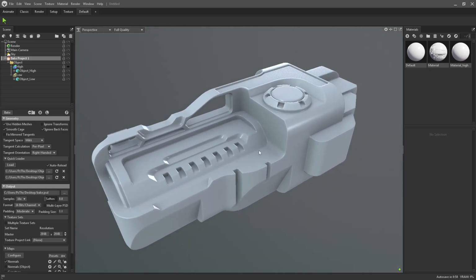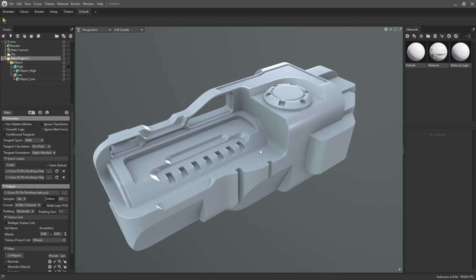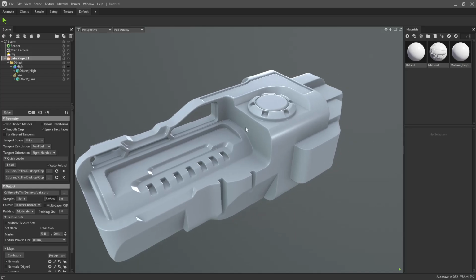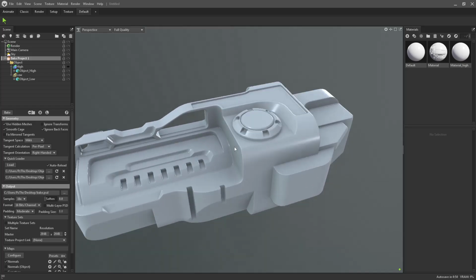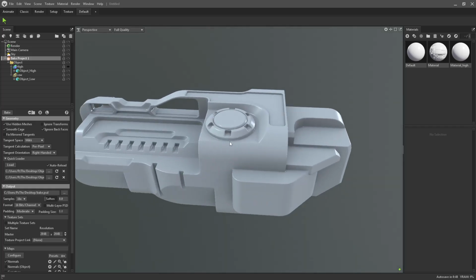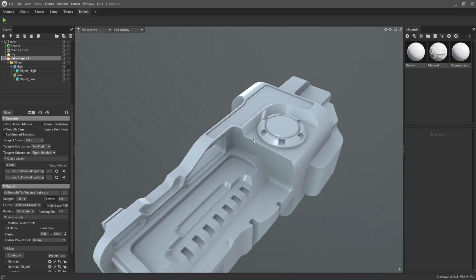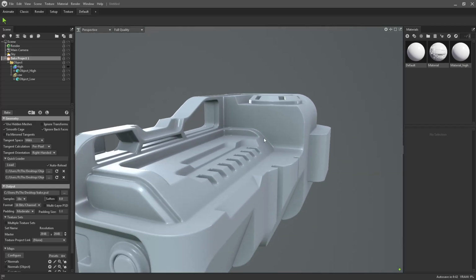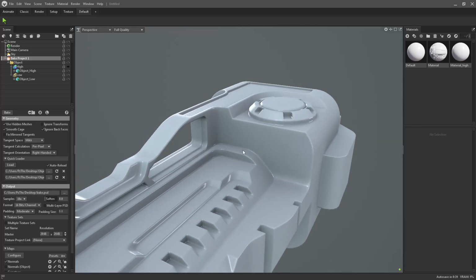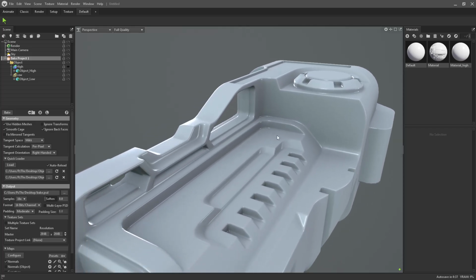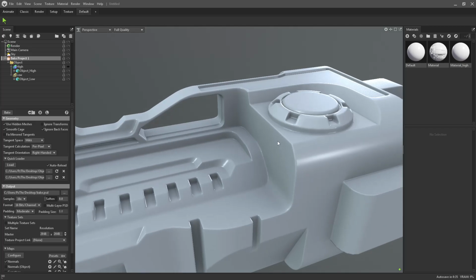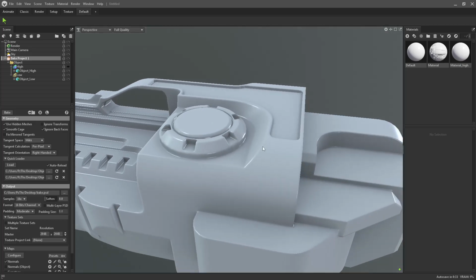But it's something you still can do if you really wanted to. But you're going to want to probably push around the cage manually, and you're going to be using triangles. It's not going to be that much fun, unfortunately, because you can't lock the triangulation into place for whatever reason. So you lose all your control on the mesh. Some of the software out there will let you lock the triangulation, but not Blender. So maybe there needs to be an add-on for that, but I think that's more hard-coded stuff, perhaps.